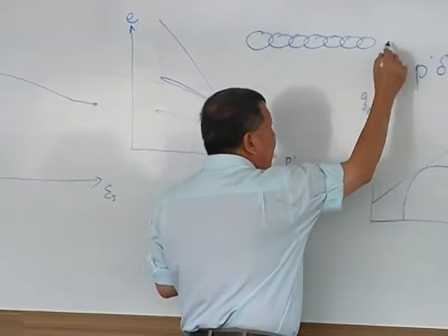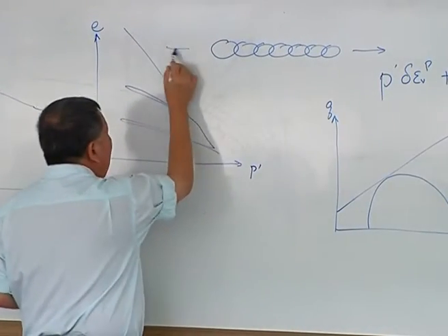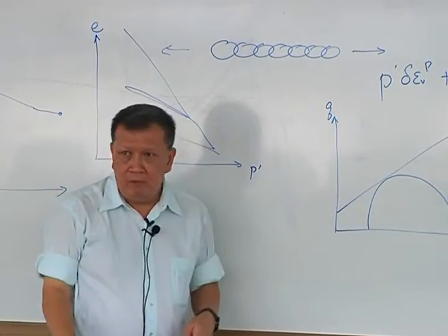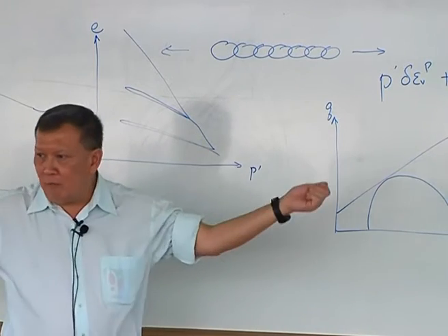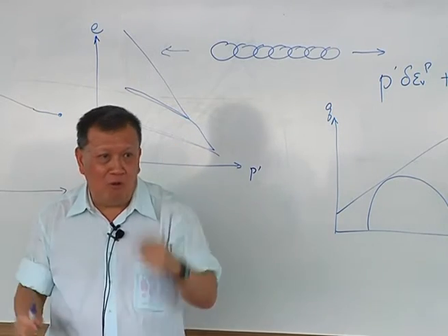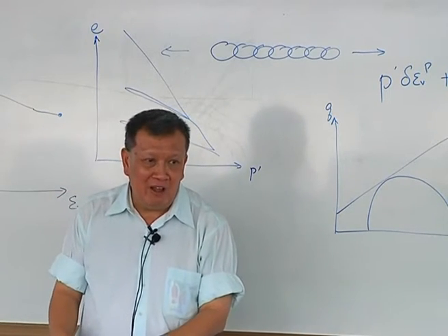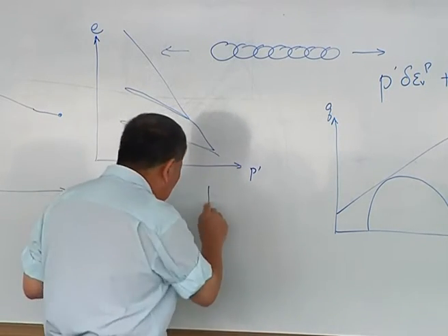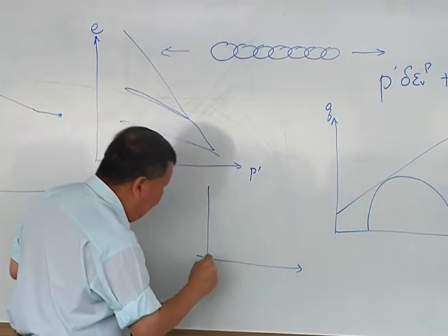So you start pulling it like this. You keep increasing the load until the chain breaks. Will all the links shatter at one time? One will go, right? One link will go. Why? That happens to be the weaker one, because the stress-strain curve of the link is like that.